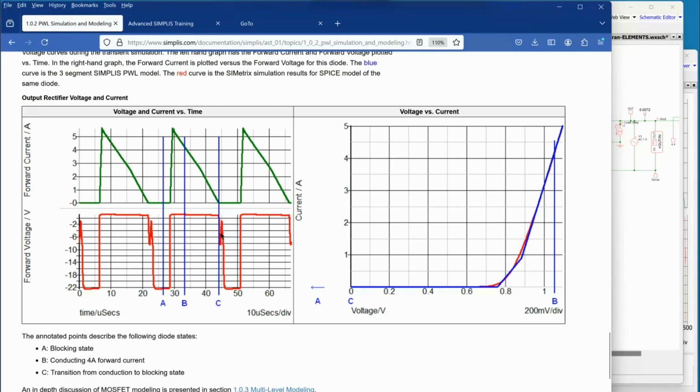Similarly, how much error happens when we're going from 1 amp down to 0? Is that error going to be significant? In this case, the answer is no. You could add another 1 or 2 piecewise linear segments to this characteristic and rerun the simulations. If you looked at the Bode plot and your step load change, you would not be able to detect the difference. And you can always run those experiments.